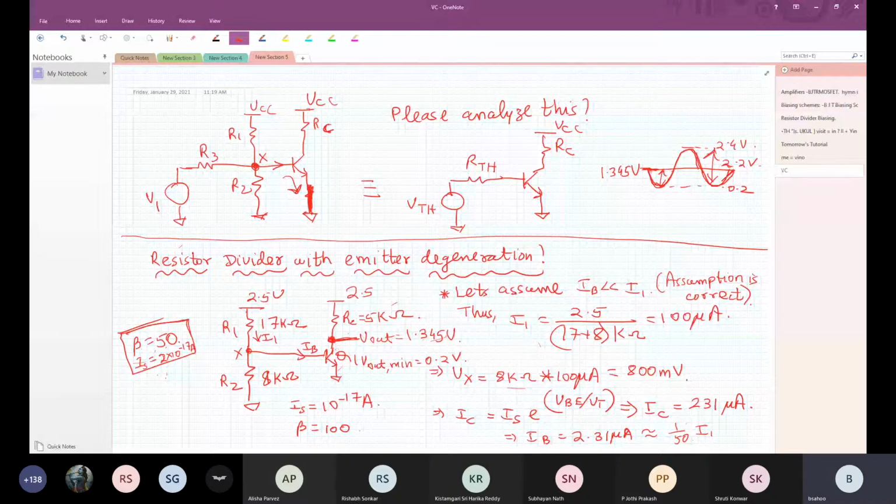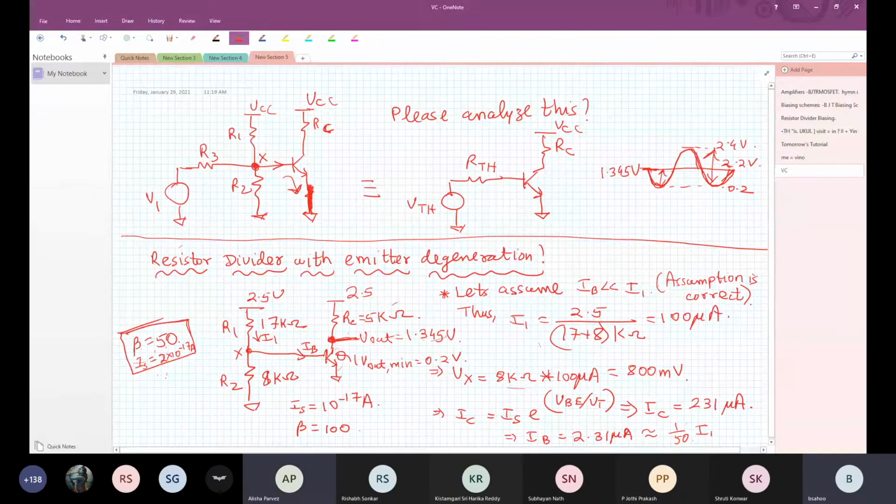Yes. I had a question about an earlier part of this question. We got the lower swing as 0.2 when the transistor enters into saturation. How did we get the upper value of 2.4? No, it will be equal, right? Whatever is coming down, I just made it, said that let it be 1.1. Okay, so it is 1.145. So then always you can add equally. It should swing from this point equally up and down. I just approximated it. Good point, you raised it.